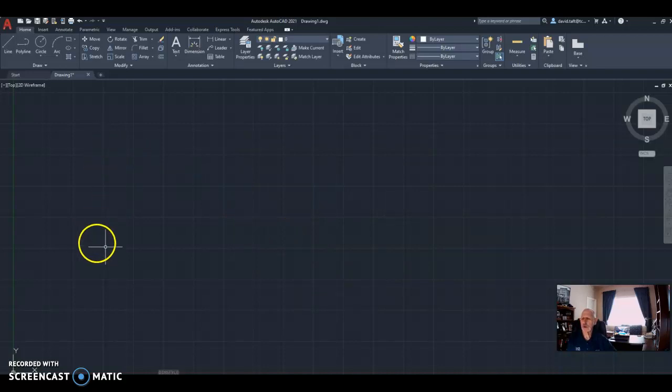I'm going to draw a title block and border, but the first thing I'm going to do is draw the sheet of paper for some control. We use an 8.5 by 11 sheet of paper. So L, Enter, or the line command, either one. I'll left click, and turn ortho on, which is F8. Now you can see the blue box asking for a distance.